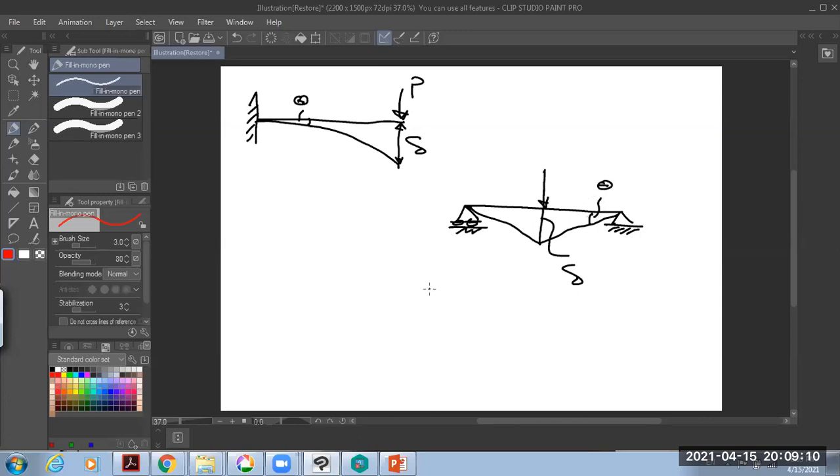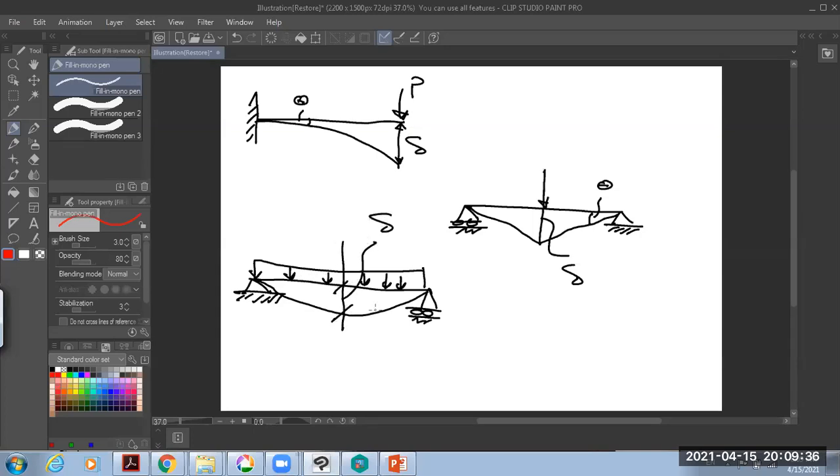Now, if you have a uniform load on a beam, how is this beam deflected? It will take a parabolic curve deflection line. We call it an elastic line. This is the deflection amount, and this is theta. Theta is always tangent to this parabolic curve. This is the slope, so the tangent here gives the slope at this point.